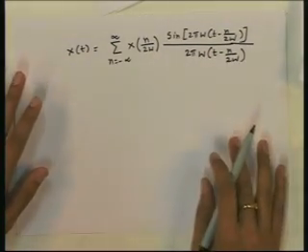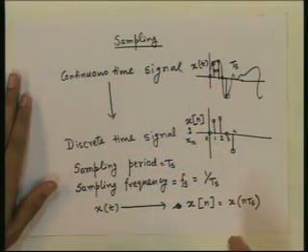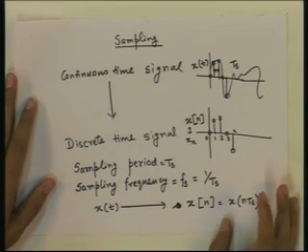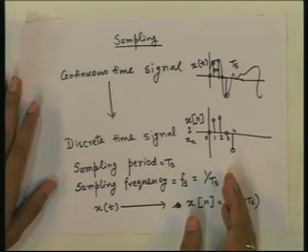Okay. So, in this class we have discussed sampling. So what is the purpose of sampling? Its purpose is to discretize a signal in time, because there are infinite number of time instances where the analog signal has values, and we cannot store all those values if we want to discretize the signal. And so, we need to pick up samples at regular intervals, regular instances, and store the values of the samples.